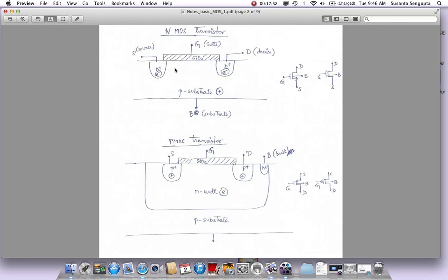Okay, so there is a diode here, N plus to P diode. This is also an N plus to P. So there are two back-to-back diodes here, and the current could only be formed by electrons, because since it's an N-type material, it's heavily rich in electrons. The only thing that could be flowing in and out of the source is electrons. The only thing that could be flowing in and out of this drain here is electrons.